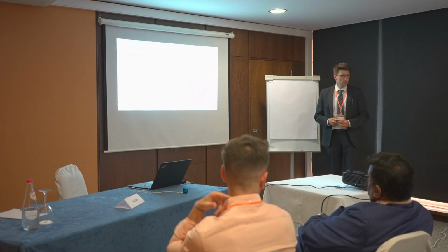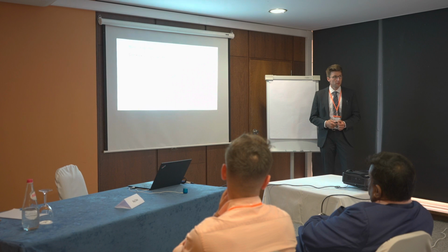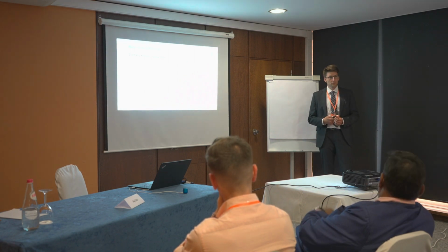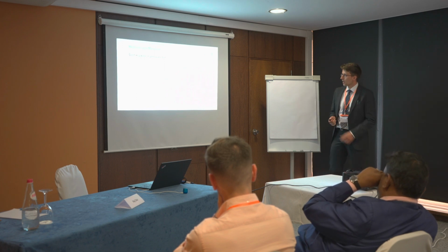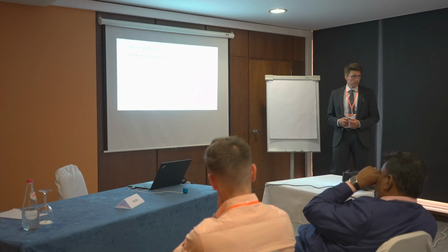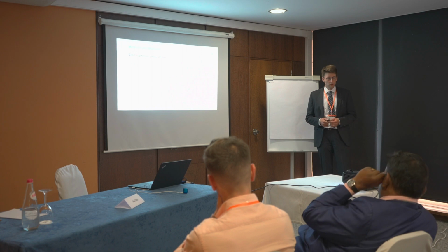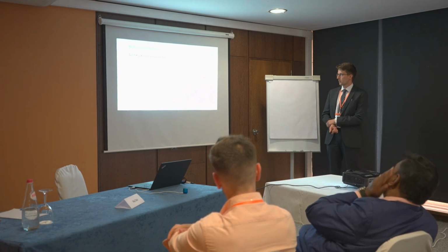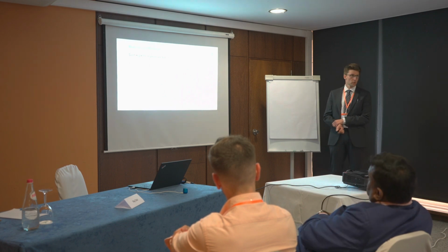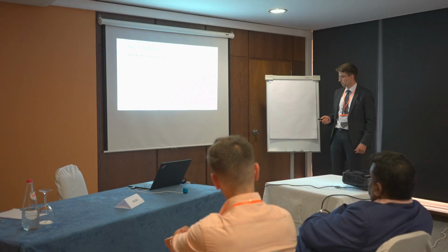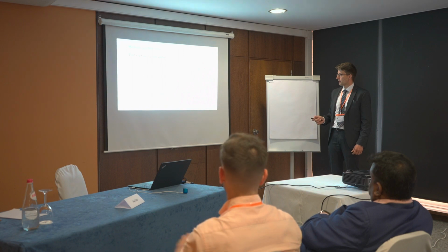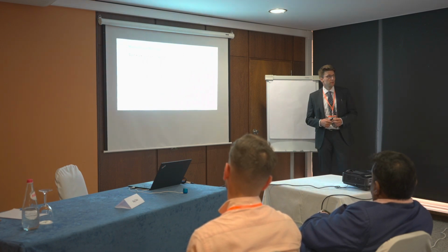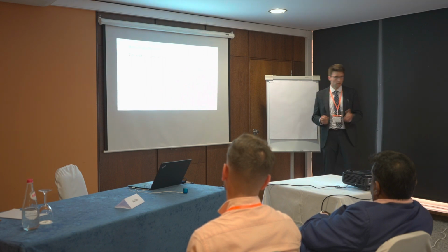So what do we measure? We measure a voltage of the strain gauges, which are applied on the surface of the bars, and we measure displacement by the optical extensometer. What do we do with these measured characteristics? We calculate the strain by using a constant which incorporates the characteristics of the strain gauges and the gain of the amplifier and so on.